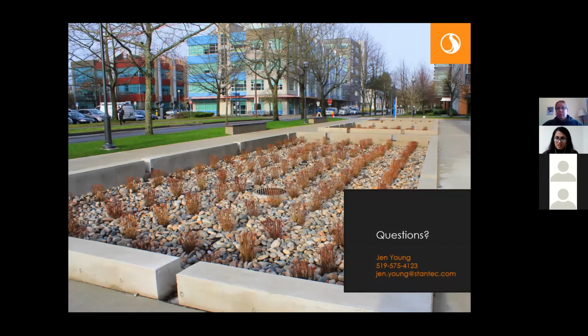He's asking, in the case of Toronto, Ontario, how will the Don Mouth naturalization project affect stormwater management in the city? And what would that mean for the city's low impact development, green infrastructure going forward? So the Don Mouth naturalization project, in a way, could be considered low impact development or green infrastructure. It is a river restoration that's going to include some created wetland areas that will help with treatment of stormwater on the port redevelopment.